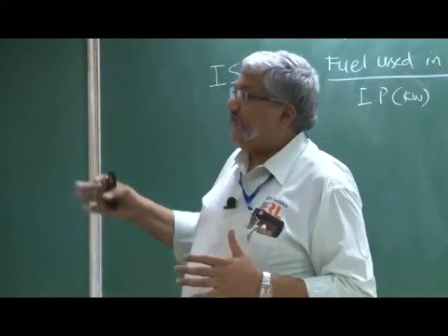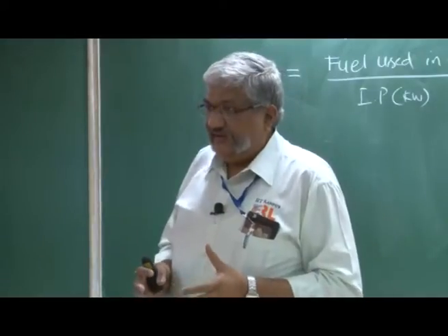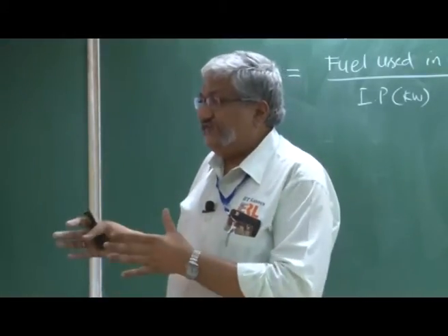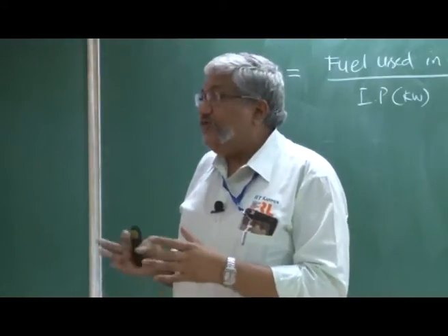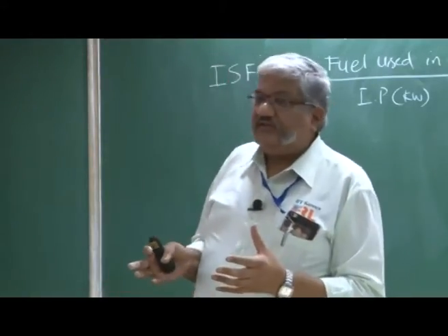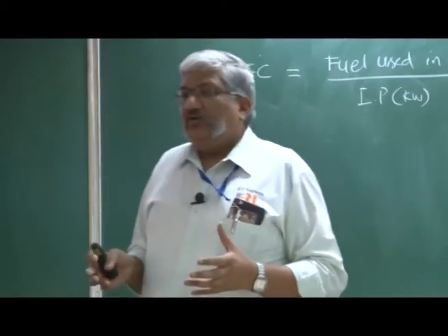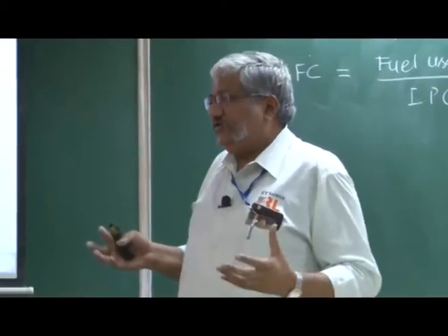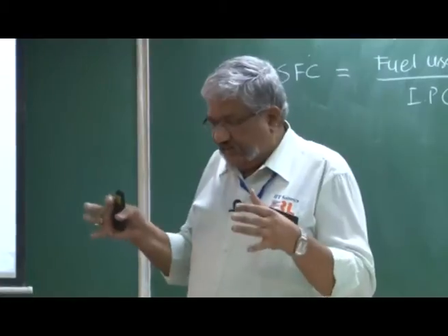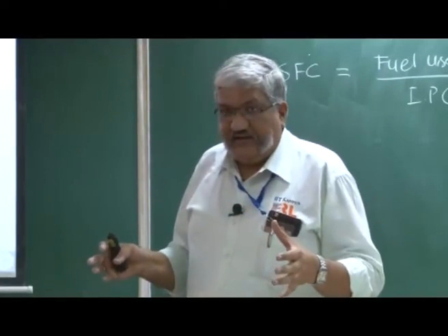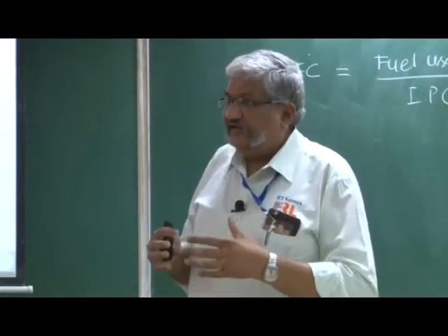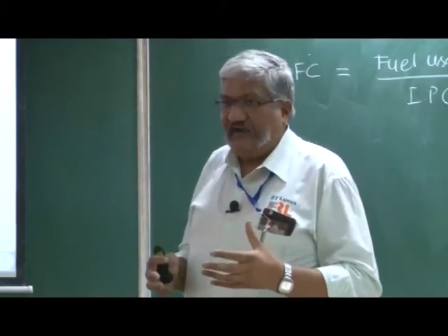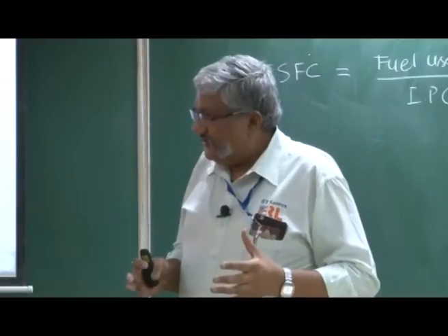And then we already studied that there is a lot of heat that is going into friction, right? And then there are a lot of unaccounted losses. What are these unaccounted losses? For example, you club all other losses into unaccounted losses. For example, when you run the engine, it is hot, right? So it is doing radiative heat exchange, right? So it has a significant amount of energy, maybe 2, 3, 4%, but it's very difficult to estimate, right?